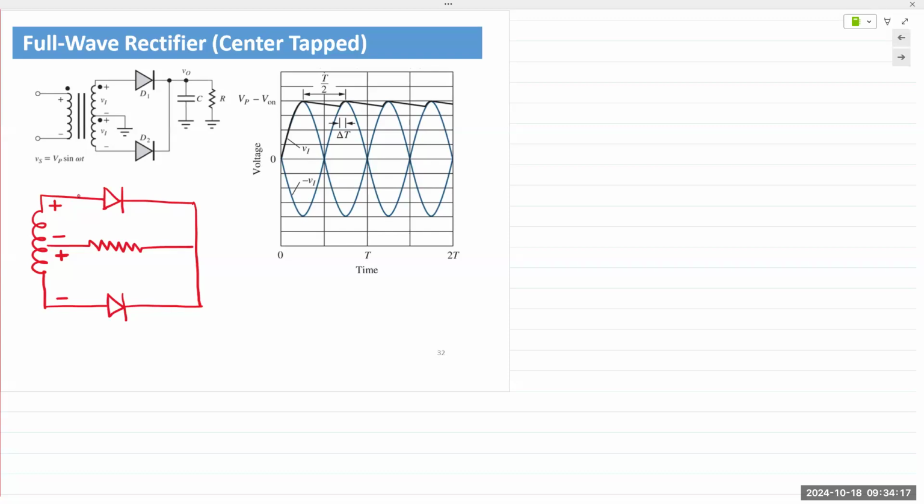So all of those are simply tappings in the secondary coil. So not center tapped, right? Obviously not center tapped because you're stepping the voltage down from 220 volts all the way down to like 15, 12, and 1.5 volts. 220 volts because I was in India. So tapping does not simply mean center tap. That's the point I was trying to make.